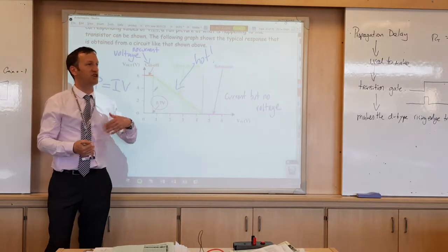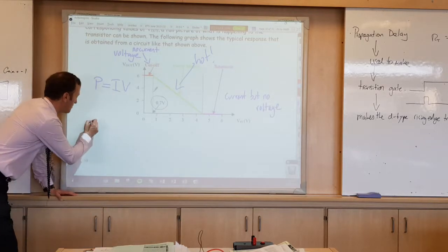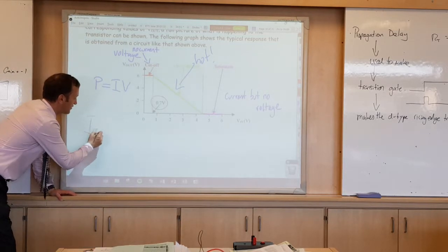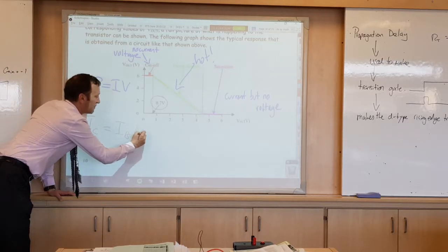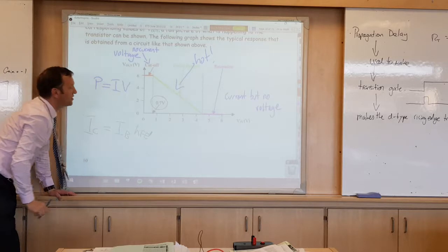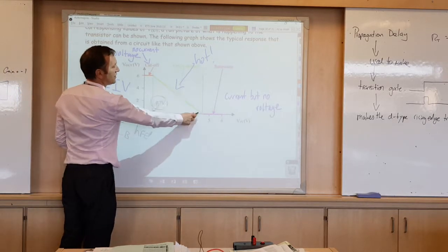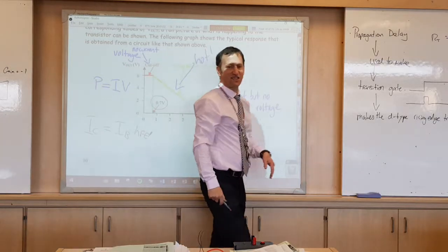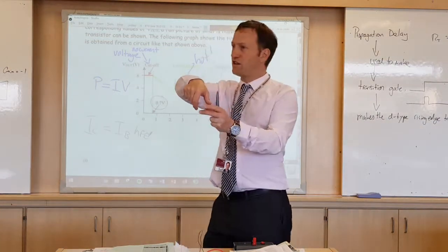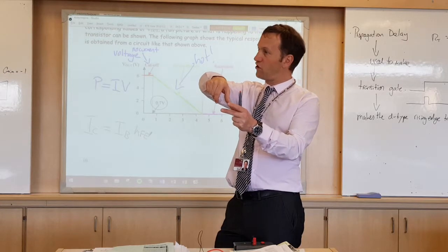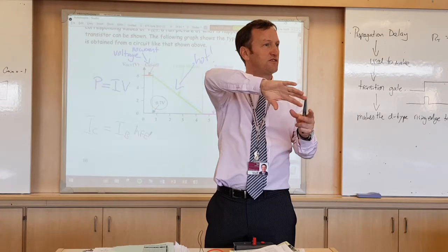and it's the part of the transistor where the base current going in is proportional to the collector current. Because remember, we've got IC, the collector current, equals the base current multiplied by HFE. That's only actually true within this region. Because once the transistor is saturated, it's like at home when you turn on a tap: at first, as you turn it, the flow gets stronger, doesn't it? But after a while, you can keep opening it and it makes no difference.